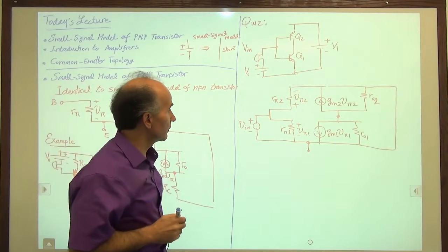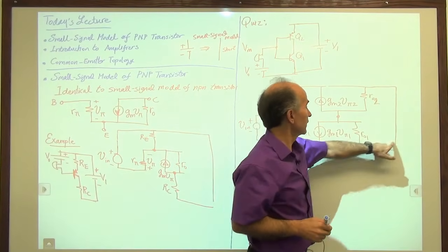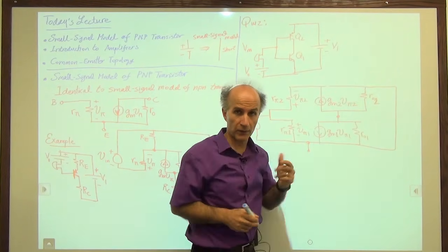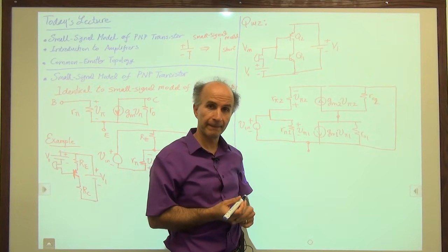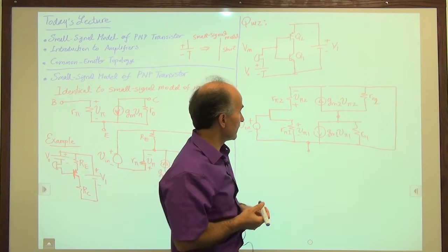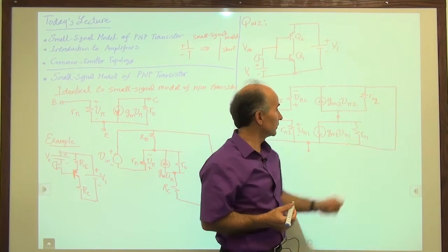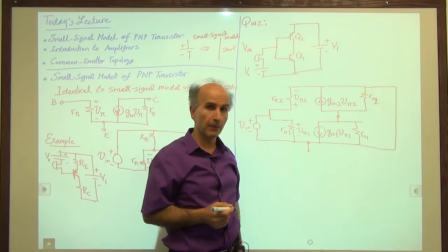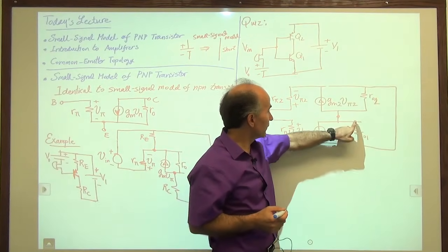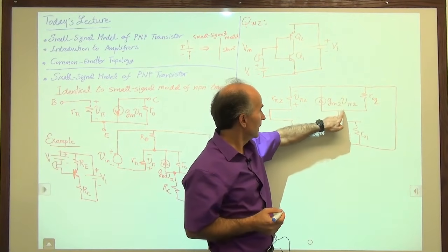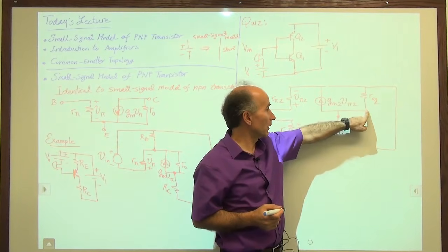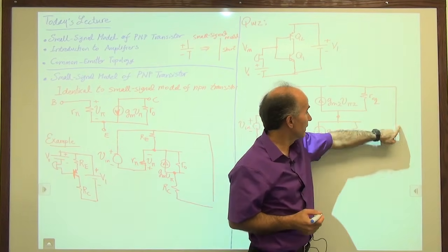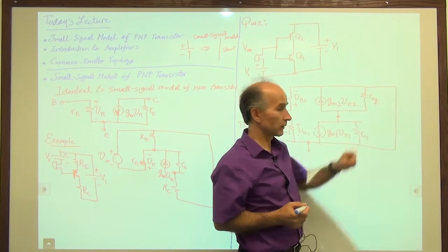All right, well, remember that there is a short circuit from here to here to represent this small signal change of this voltage source, this constant battery. So then let's examine RO1 and RO2. What can we conclude? Well, we see that the top terminal of RO1 is shorted to the bottom terminal of RO2, and the bottom terminal of RO1 is shorted to the top terminal of RO2.